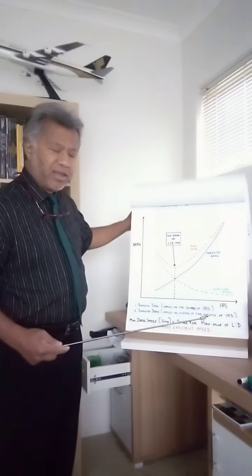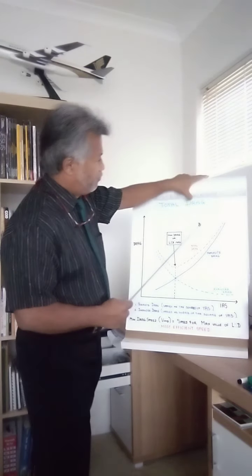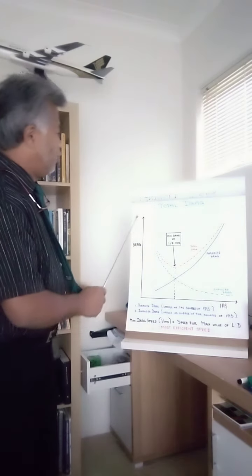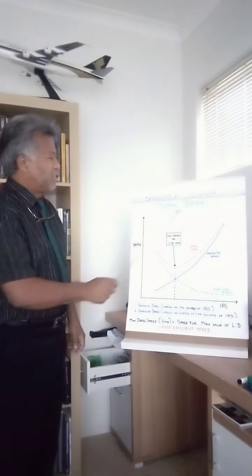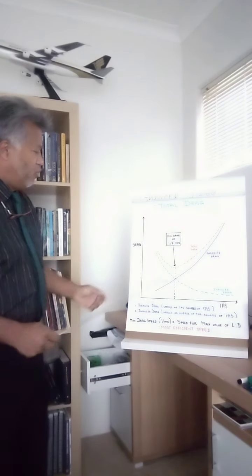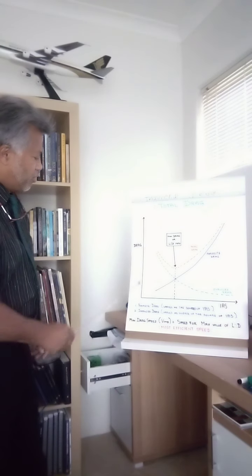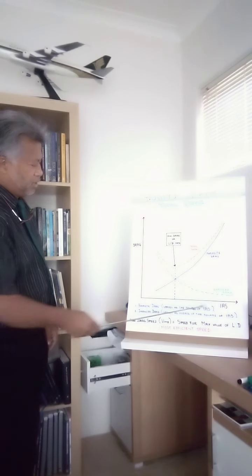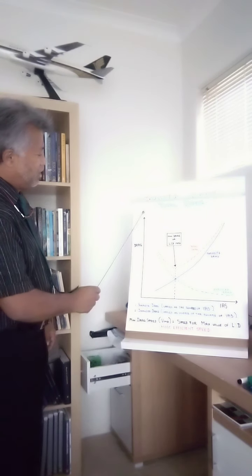Going back to the drag, which we talked about before, the parasite drag and induced drag become now the total drag that is acting on an aircraft or an aerofoil. If we have a graph to depict that, you will see the airspeed increasing this way and drag increasing this way.